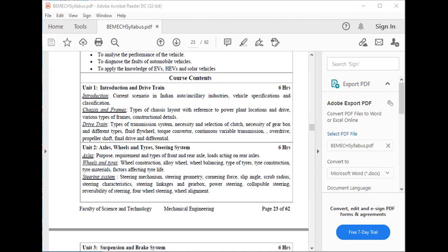If we see the flywheel, it is attached to the crankshaft flange. Its mass is used to store energy, and it has a machined surface on which the clutch disc connects. It has a ring gear on its circumference, and the pressure plate is bolted to the flywheel.